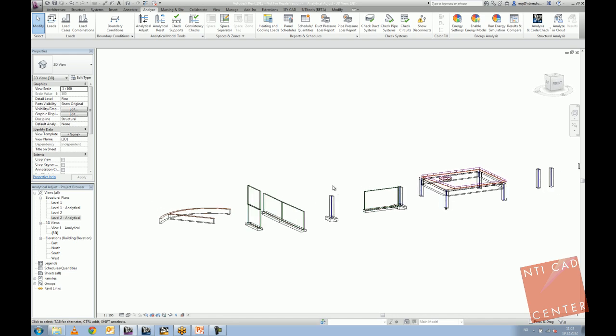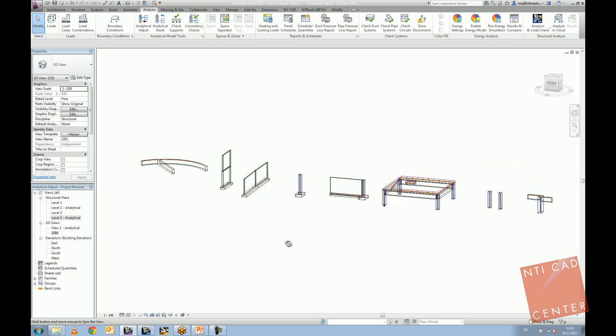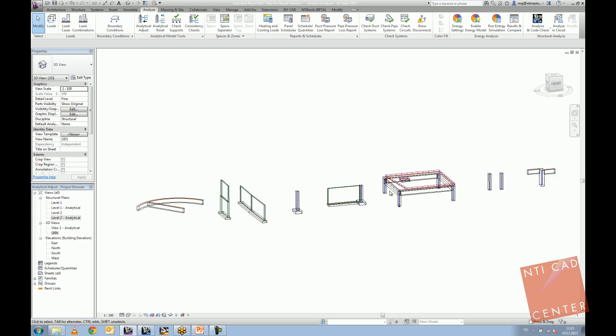So that's pretty much all about the analytical model in Revit. Again, how you can control it and how you can make a more accurate model. In general, most of the model is actually done quite okay the first time, automatically, with Robot. But again, sometimes you just need to do this analytical adjustment. So with every project, there is always a little part which you need to do manually. And again, it's always easier if you have this control from the very beginning of the project.